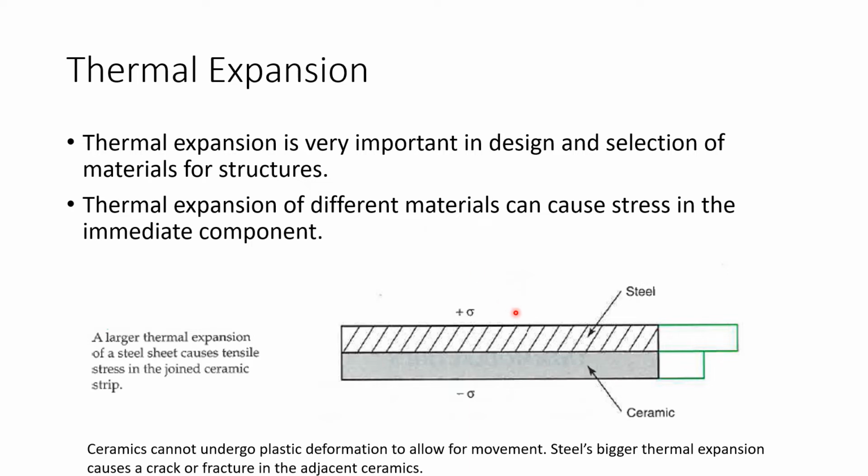So here we have thermal expansion, very important in designing, because if you make a mistake in calculation, you're going to get the whole design wrong and they're going to mess up every time the temperature changes. So you have to include the temperature change and thermal expansion of your material in your design and give them some space.